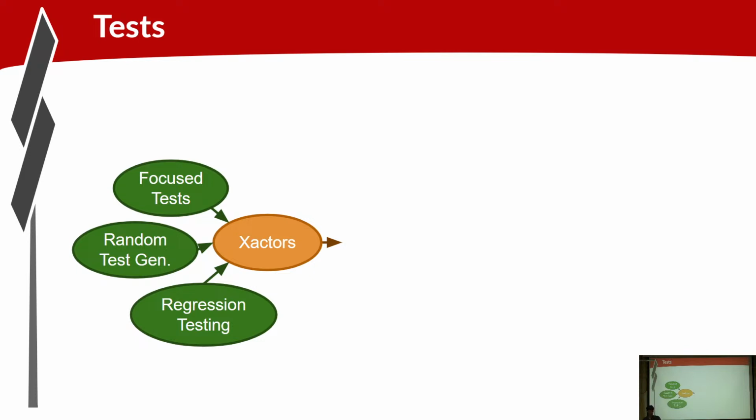Obviously, you want to balance the magnitude of regression tests versus the quality of the tests. You don't want regression to take 3 days to run. That's going to slow down progress on getting changes in, but you also want them to get good enough coverage that you don't have bugs creeping into your design that was once stable.